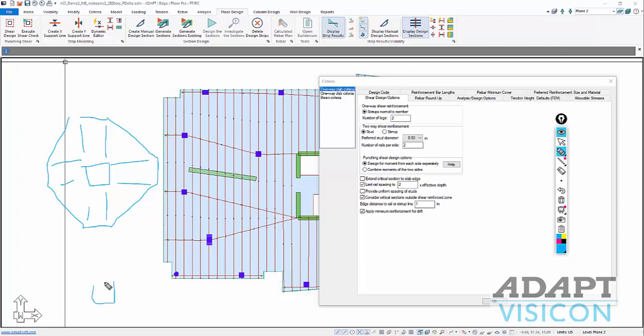Now, if we had reinforcement off of a diagonal, obviously this changes the critical section. Then our least critical section looks something like this. So it's rectilinear versus octagonally shaped.